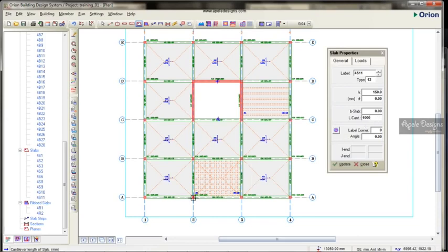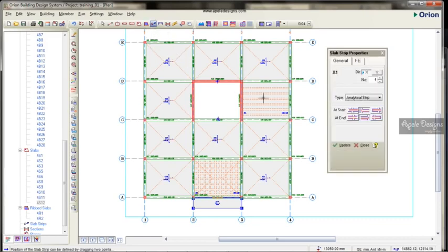Then from left to right, this is the cantilever. Next thing we do is to create our slab strip. Click slab strip, and this means that our strip starts from a slab and ends in a slab, or starts from a beam edge and ends in a beam edge, or it starts from a cantilever or ends in a cantilever.